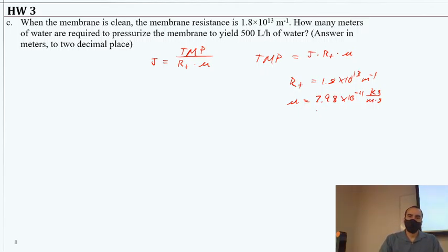Okay, but you had it last time. With these lookup tables, just keep in mind the table itself, where it describes the units, has the 10 to the minus third in the unit. So this looked like 0.0798 or 0.798, but the units are times 10 to the minus third kilograms per meter per second. So the dynamic viscosity in the units that we use is going to be a small number. It's going to be times 10 to the negative third or fourth. So just keep that in mind as you're working the problems.